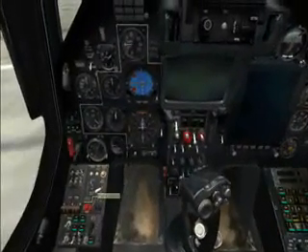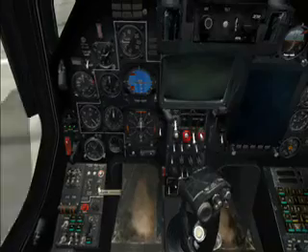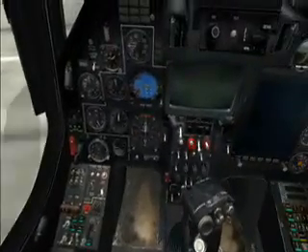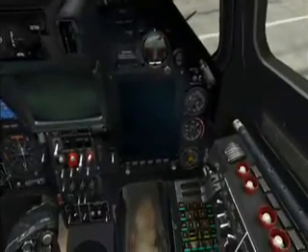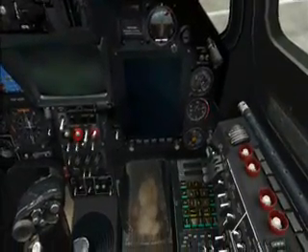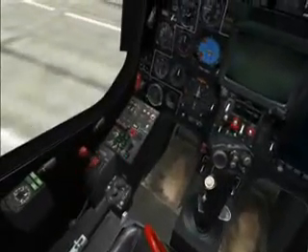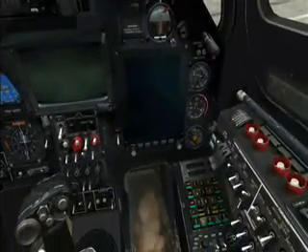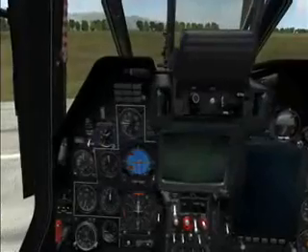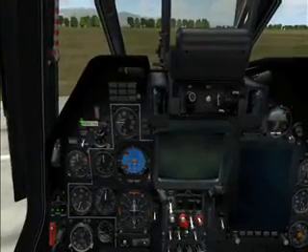So we'll place the engine select switch in the lower right, and click the engine start, and we'll wait for the other needle to get to about 1800 RPM, and then we'll open up the engine shutoff valve. And again, like the left engine, we'll wait for that to get to about 7000 RPM. While that's going, we can test the lamp indicators. Those are all looking good.